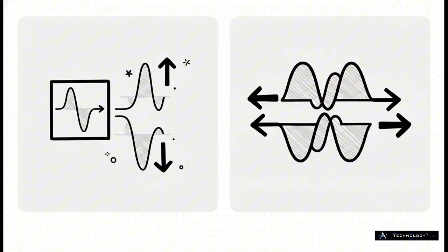That unique twist the system applies comes in two distinct flavors, magnitude and phase. Magnitude refers to gain or attenuation. Basically, does the system make the input wave taller or shorter? Phase shift, on the other hand, refers to the time lag or lead. Does the system delay the wave or sort of push it forward in time? These two parameters completely define the steady-state personality of our system, but how do we actually find them mathematically?